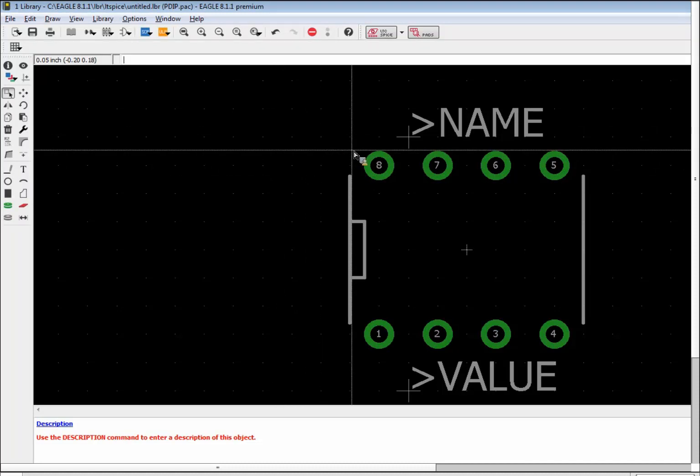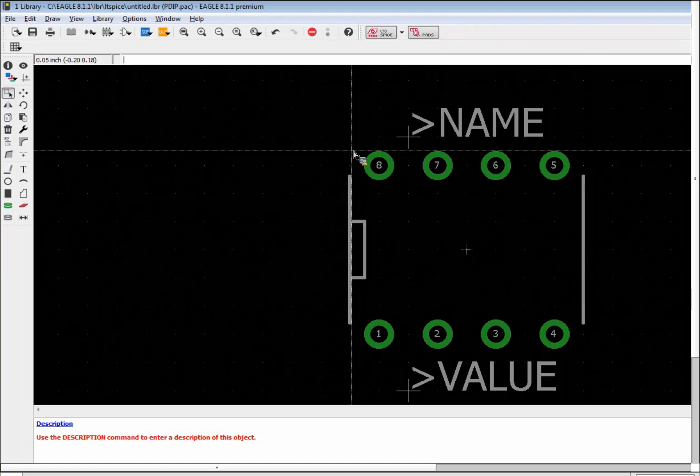So probably in the next webinar we will be going more in depth into arbitrary pad shapes, but just to give the idea, basically the way arbitrary pad shapes work in Eagle is that either a pad or an SMD object defines the connectivity. So when you make the arbitrary pad shape using a polygon, within its borders there must be either a through-hole pad or an SMD. If there is, Eagle will consider the polygon an extension of that pad and therefore won't generate DRC errors on it in the board and when you make connections to it.